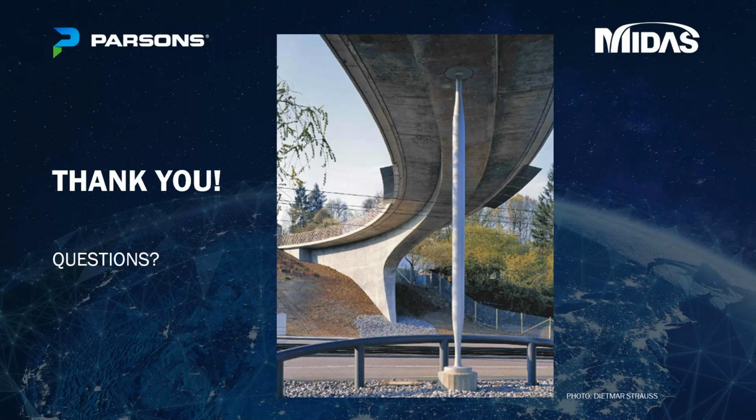So having a post-tension or a girder in a curved configuration is absolutely possible and it's not creating headaches. The problem is pre-stressed concrete doesn't crack. It's not supposed to crack under service load because you want to protect your tendons. And when your concrete doesn't crack, it's much stiffer. And that stiffness hurts you when it comes to integral bridges because you actually like the bridge to crack.